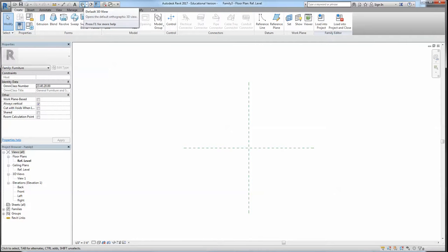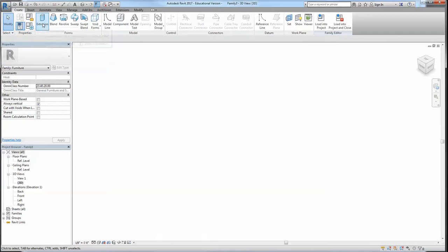I'm going to go to the 3D space and create an extrusion. The way this family and many others like it work is that you always start drafting curves, so you need to know in what reference plane you are drafting those curves first, and then say yes, extrude it. It's a little bit similar to conceptual masses, but more self-intuitive because it tells you every step how to do it.